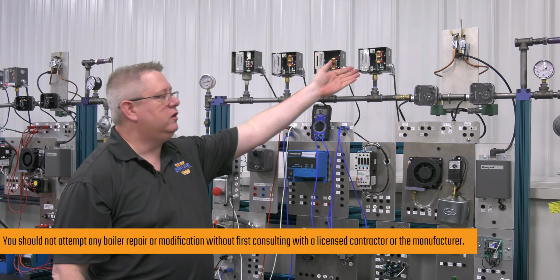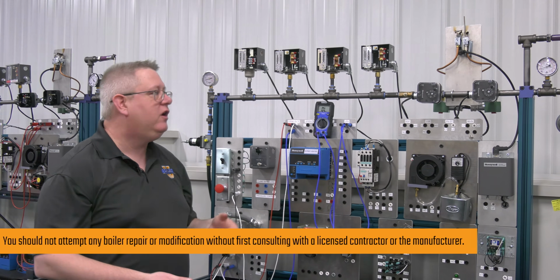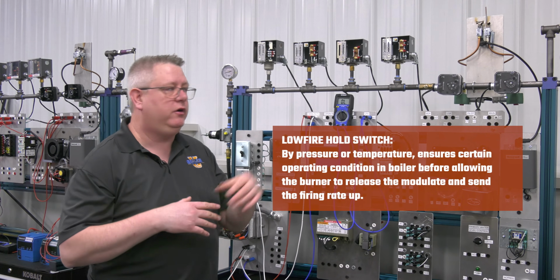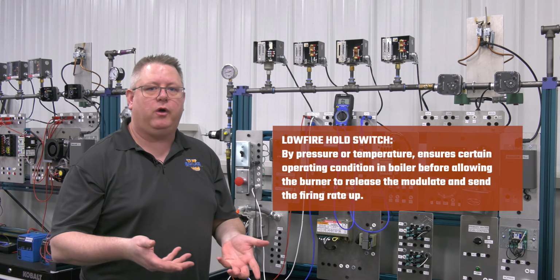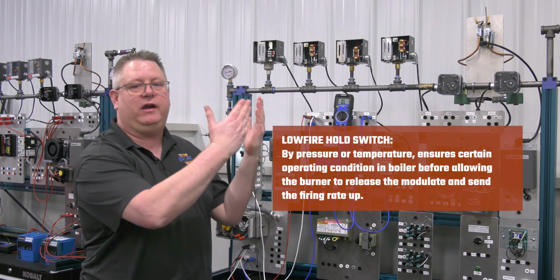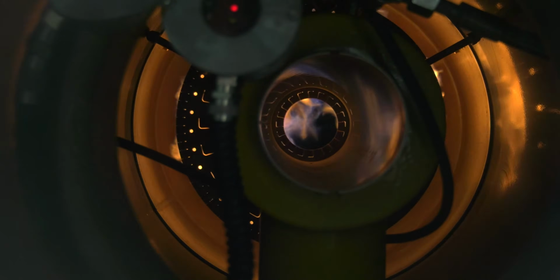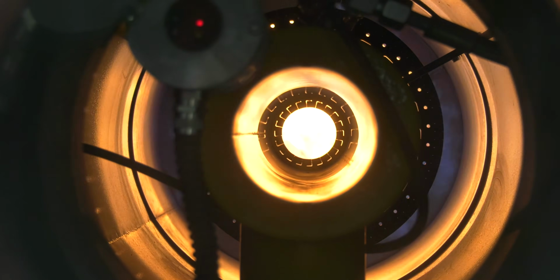We're going to talk about a low fire hold switch. Now, not all boilers will have a low fire hold switch, but it can serve a pretty helpful function. The point of a low fire hold switch is by pressure or temperature, pressure in this case, that we ensure we have a certain operating condition in the boiler before allowing the burner to release to modulate and send the firing rate up. And the obvious situation we would want to avoid is somebody turning the burner switch on a cold boiler and for it to go directly to high fire, thermally shocking the boiler.